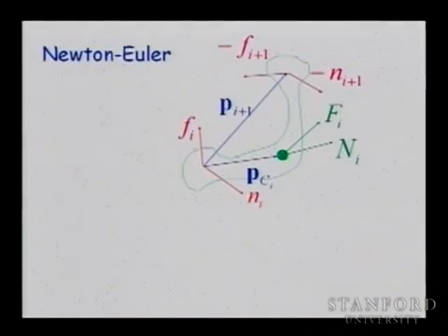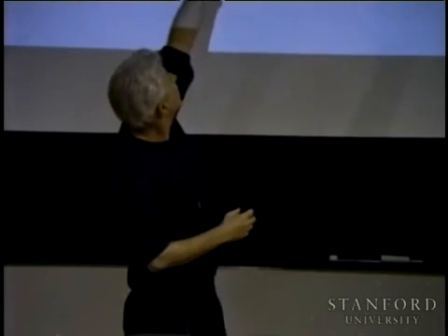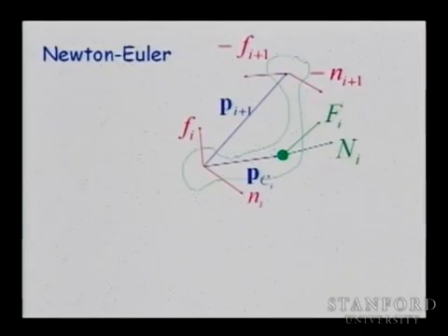So that is a very different way than the way Newton and Euler formalize the dynamics, which relies on the fact that we take each of these rigid bodies and connect them through reaction forces. So if you take all the links, and if you remove the joints, you get one link, but when you remove the joint, you substitute the removal of the joint with reaction forces, and then you can study all these reaction forces and try to find the relationship between